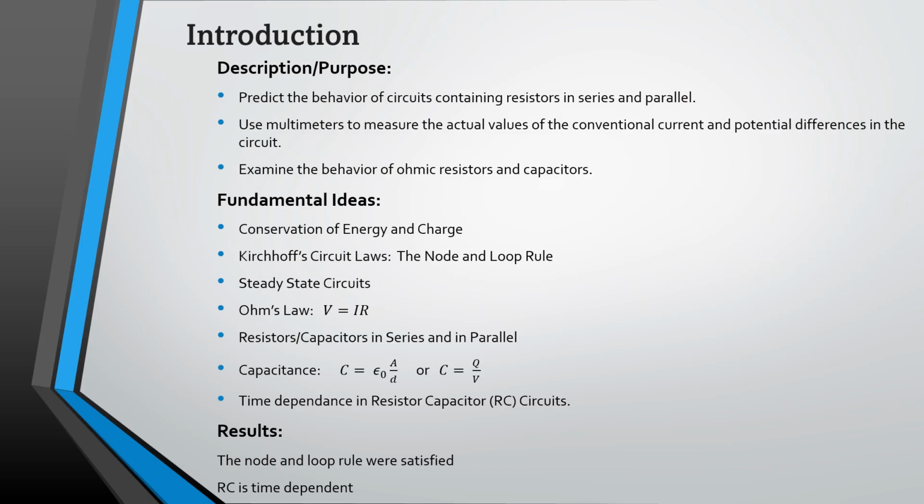Description/purpose. Predict the behavior of the circuits containing resistors in series and parallel. Use multimeters to measure the actual values of the conventional current and potential differences in the circuit. Examine the behavior of ohmic resistors and capacitors.